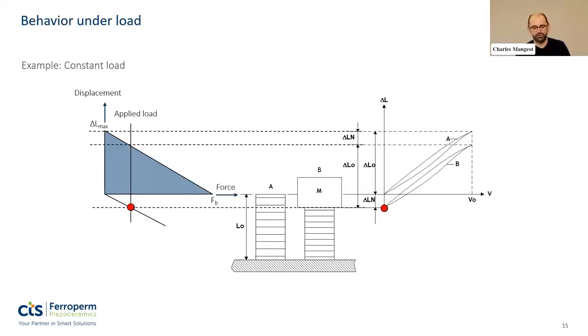Obviously, you're putting a load on it. And then when you apply the nominal voltage, the actuator will try to go to the upper curve of the characteristic. And what's going to happen is this. It will just go up at a constant force. And you realize here that in that linear model, the actuator actually moves with the free displacement, right? So you generate the free displacement.